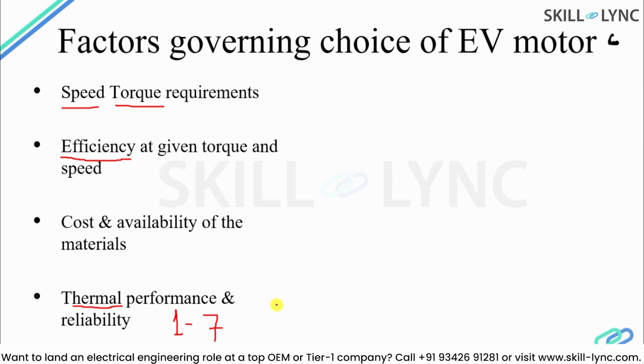So based on the drive cycle, the motor is required to produce the power, and because the drive cycle speed is continuously varying, you never know how you will drive your vehicle, right? It depends on many conditions. It depends on the traffic, it depends on environmental conditions, and so on. So how you are going to drive your vehicle is going to affect the overall thermal performance, right? So the thermal performance may actually affect the life of the permanent magnets, right?